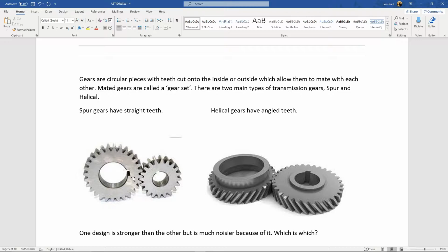So that's important to know. There's no such thing as first gear. And when we get into the automatic and you put it in drive, there's no gear in that transmission that is drive. There's a combination of gears that achieve drive first or drive sixth, or the Genesis drive 12th.